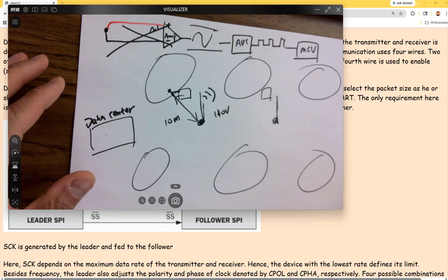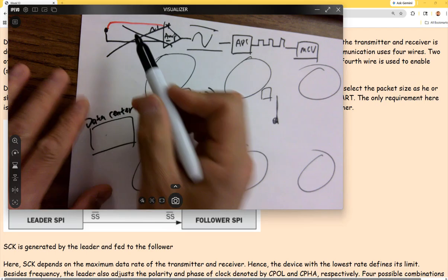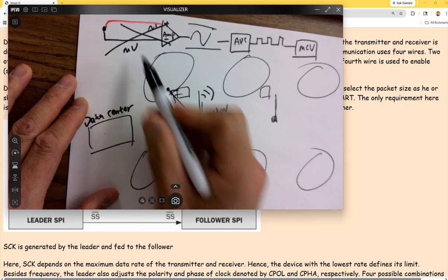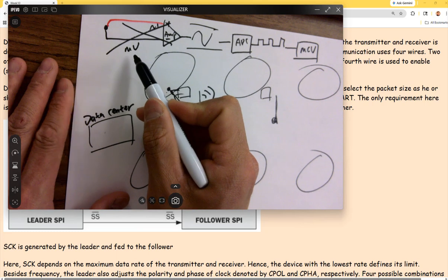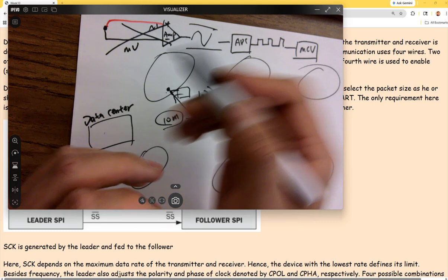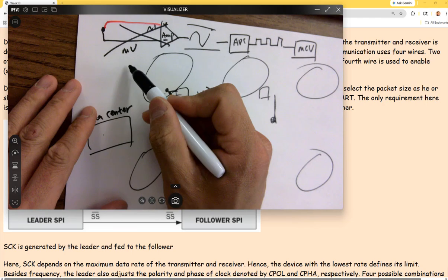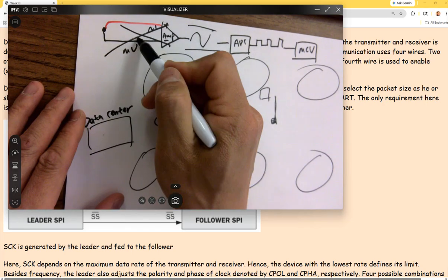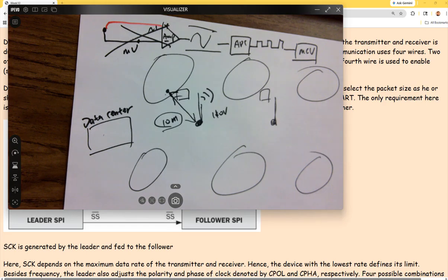Probably lose a lot of accuracy. Yeah, because these are millivolts level, and you are having a 10-meter transmission line for millivolts. That's crazy. All the noise, even if someone steps onto the concrete, that kind of vibration will get into the wires and will give you like 10 millivolts changes. And your signal is only like a couple millivolts. So that's not good. So never do long distance analog signal transmission. You should digitize it as soon as possible.